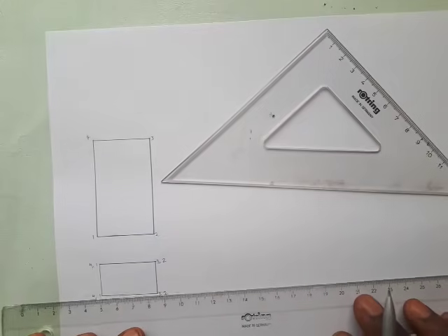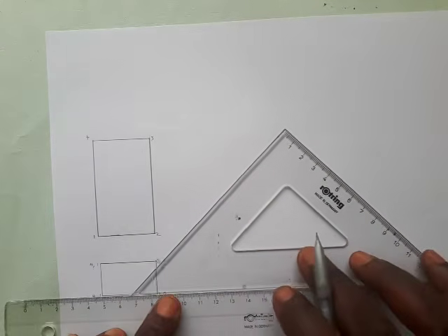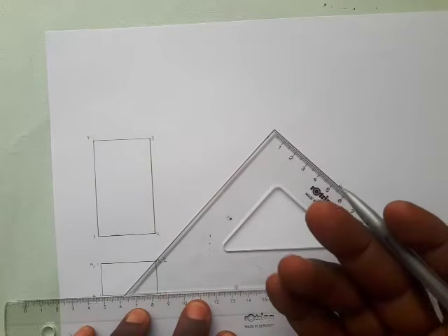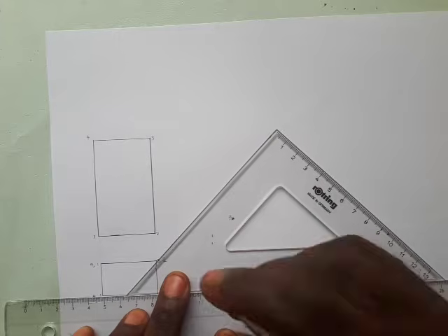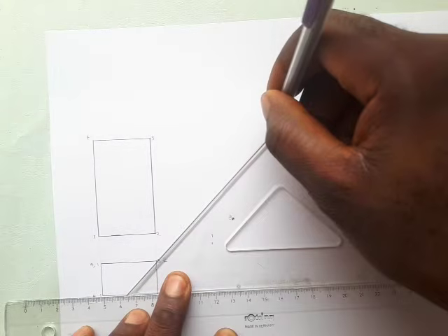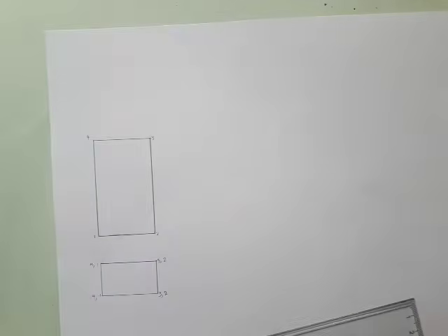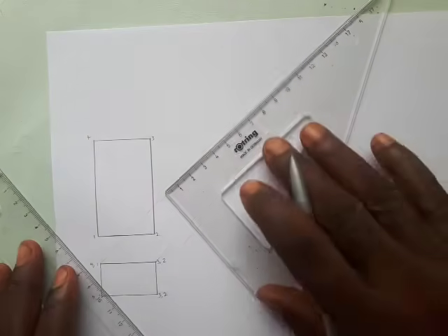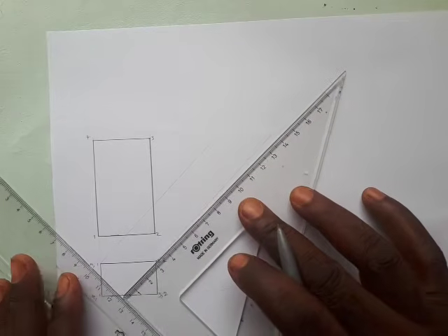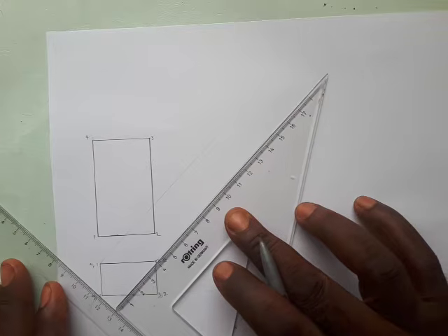Okay. So align your set square with this horizontal and place your 45 degree set square like this. So you can start with a line and draw the other ones later. So draw from this edge, thin line, not thick. Transfer to this other one here. So it's fine. I will transfer the other lines. So align your set square with any of the lines you have transferred, either this one or this one. They are all parallel.